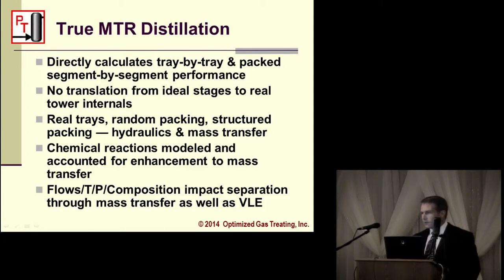So not only are we accounting for vapor-liquid equilibrium, that gives the driving force for the rate model, but flows, temperatures, pressures, compositions also impact the actual separation that will take place by leveraging mass transfer also. Hopefully this will be a little clearer as we get through.